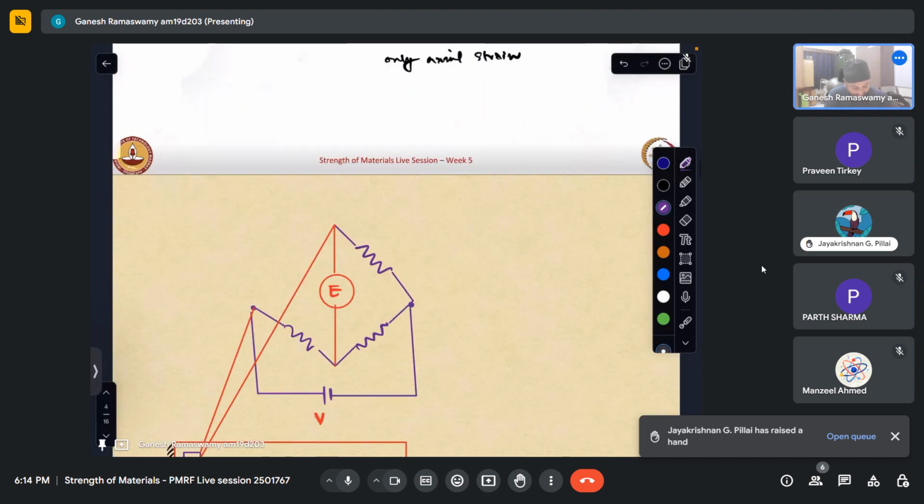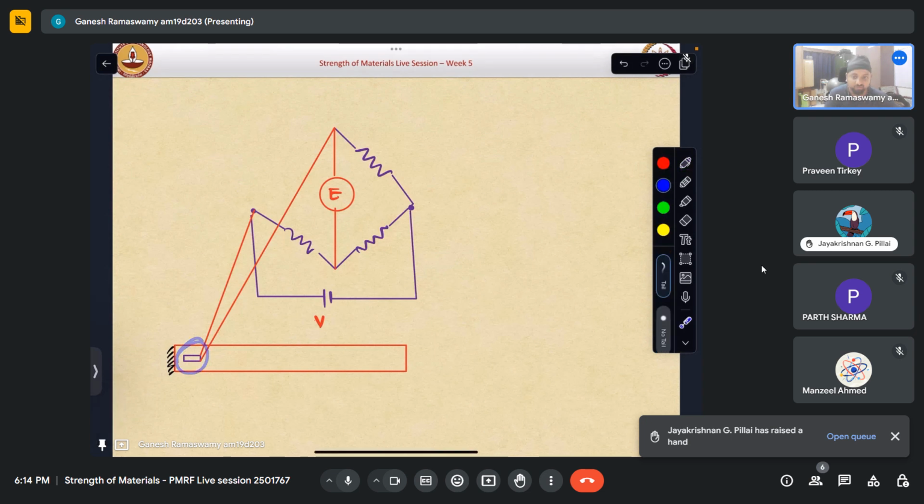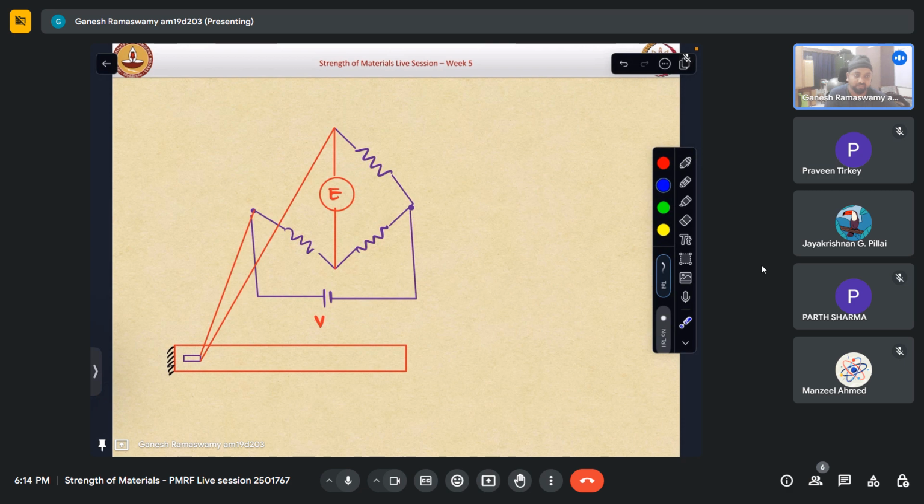No, essentially, this resistance is not the only thing that plays a role in this, because initially we have to balance out the bridge also. The most common application we find is 120 and 350 ohms. But for special applications, because the Wheatstone bridge needs to be initially balanced, and we will see later that in order to maximize the efficiency or the signal of the Wheatstone bridge, it is preferable that all the resistors are of equal resistances. So considering that also, we need to decide on the strain gauge. It is not just that we can blindly go up and take a higher resistor. So considering all the possibilities, we'll have to take a call.